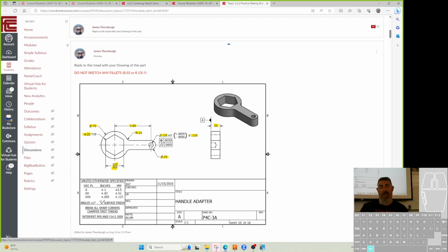I don't want to do the math to come all the way out here and then add the fillets in, right? Because now I have to do the 1 inch plus half of a quarter. So now I have to make it 1 1/8 inches. I don't want to do the math. It's easier to draw the curve and give it a dimension to the center of the curve, right? Does that make sense? Yeah.